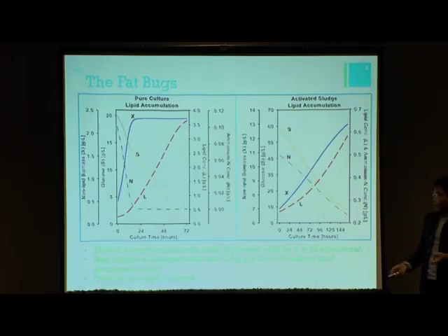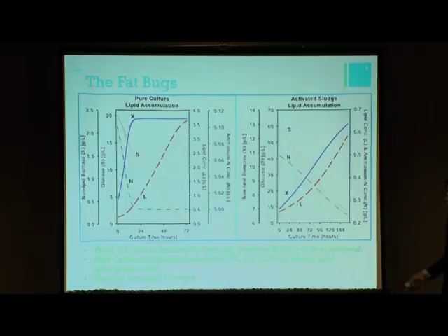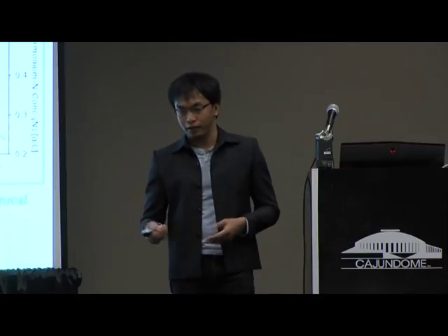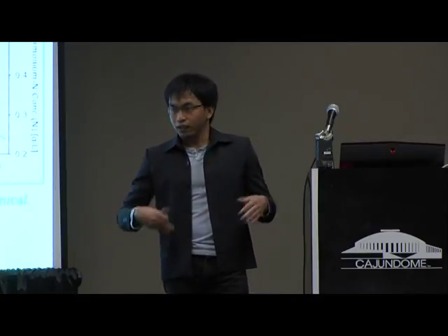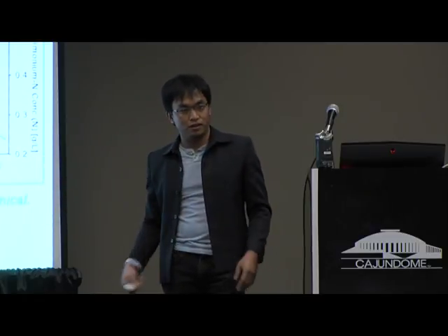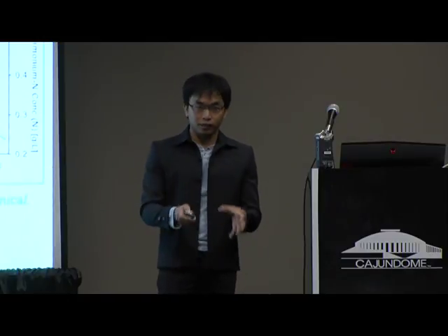By utilizing the principle of a high carbon to nitrogen ratio, a high C/N ratio, greater than 70, that's a mole ratio, the microorganisms can be induced to accumulate these lipids. I'm going to make an analogy to the human scenario. It's like taking in a lot of carbohydrates. If you take in a lot of carbohydrates, you get fat. And that's also the principle for the microorganisms. If you feed them with a lot of carbon sources, they get fat, and they can be the sources of the oil.